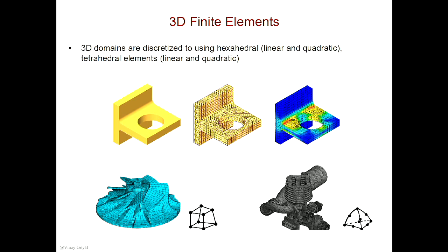stresses of the system. In this case, there's two competing stress concentrations. There's one at the fillet radii, if I were to apply a load this way. And there's also a stress concentration from the hull. It turns out that in this particular problem, the stress concentration from the fillet radii is much more important than the stress concentration at the hull.